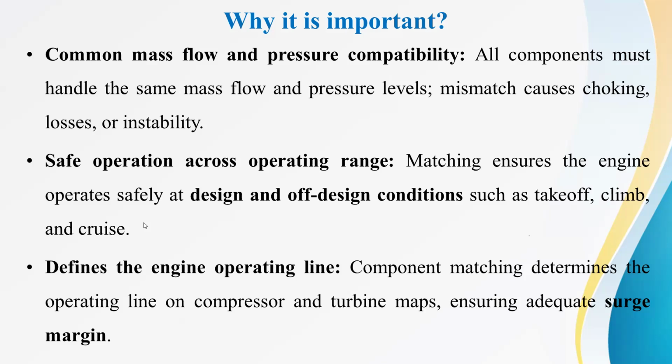Another purpose is to define the engine operating lines. Component matching determines the operating line on compressor and turbine maps, ensuring adequate surge margin. The stall margin must also be defined.